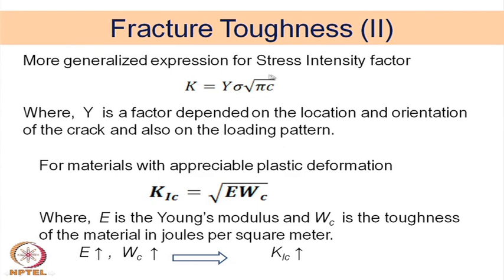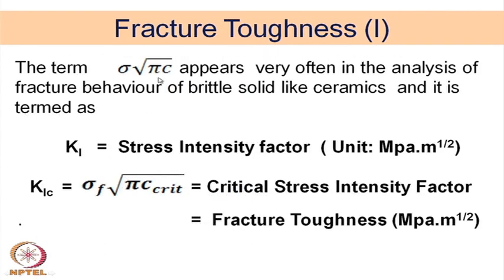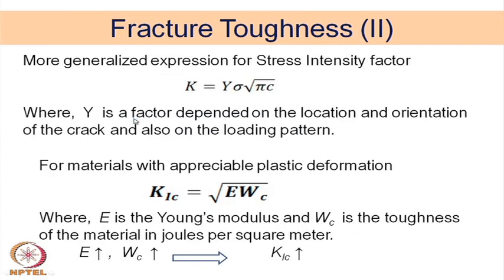More generalized expression of stress intensity factor, that was a simplified factor. Okay. This is the stress intensity factor, where there are only two terms, sigma and C. However, a more rigorous analysis shows that there is another multiplying factor. In addition to these two terms, there is another multiplying factor, Y. Y is a factor dependent on the location and the orientation of the crack, and also on the loading pattern.